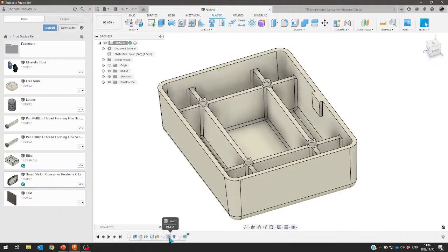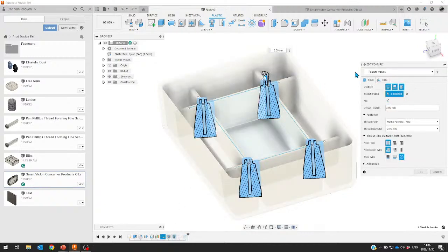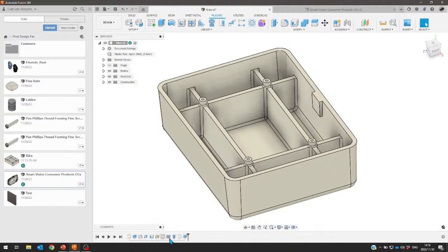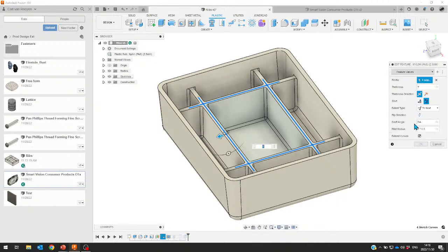Now, from a presets perspective, we're able to go into a command. We're getting a little bit of a sneak peek here at the boss command, and you can drop down and you can choose last used values, Fusion 360 default, or the values that are currently set for this feature. However, let me go have a look. So one of these features, I do have a predefined preset. So here we see my draft. That is my preset that I created.